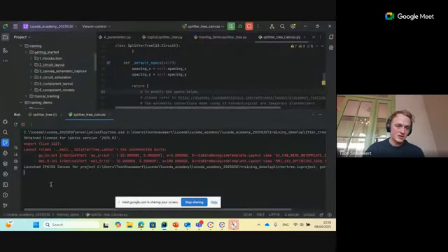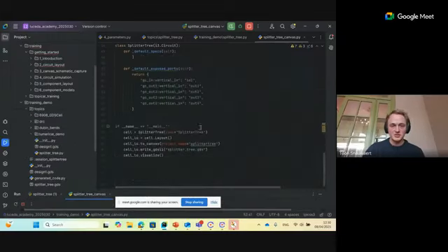But you will also see that we create an error message that there are unconnected ports. These two ports are unconnected, so they should probably be connected. So this is a great way, using the toCanvas methods, to check the connectivity of your photonic circuit.